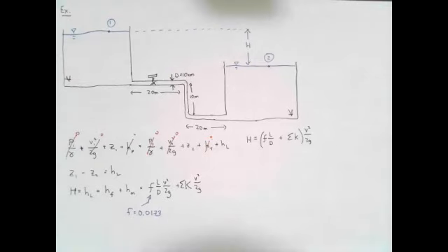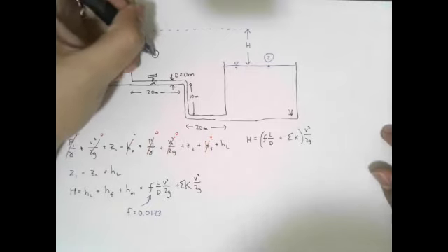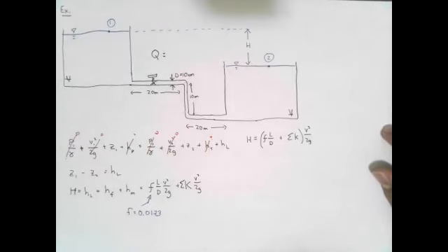When we're dealing with pipe systems, you'll notice that in engineering, we don't really deal with velocities because any change in diameter changes your velocity. That's not very helpful for us. Instead, we deal in terms of flow rate. Typically, our systems are designed to convey flow at a specific rate.